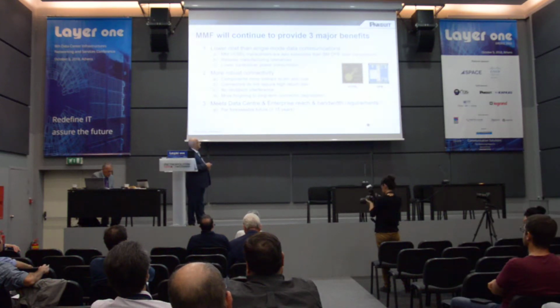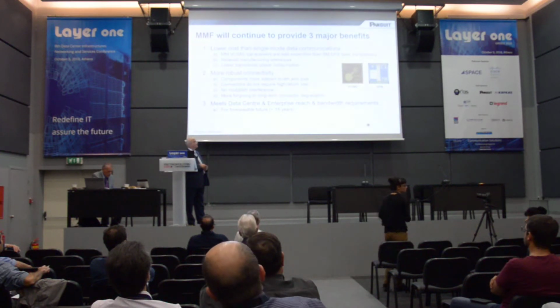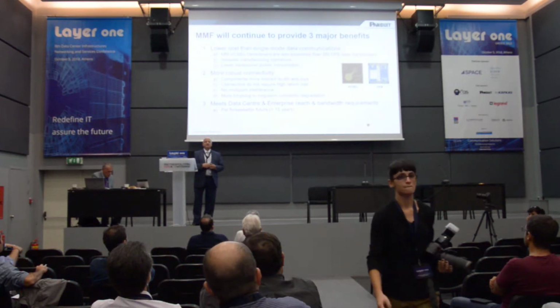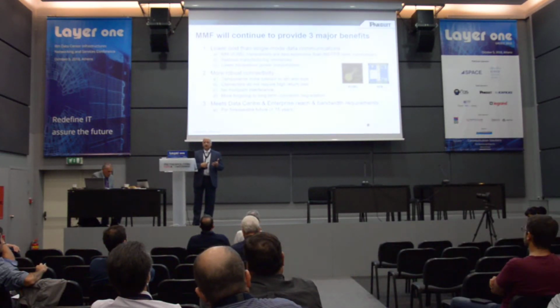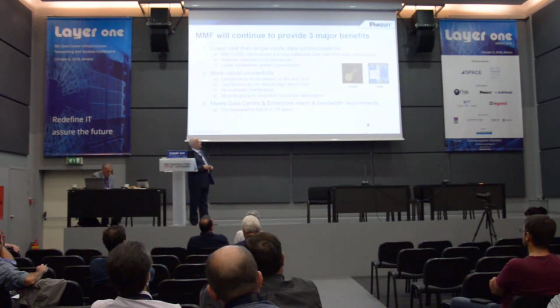I have an image here. This is a VCSEL. This is a distributed feedback single mode laser. The difference between single mode lasers and VCSELs is that DFB lasers are edge emitters. All single mode lasers are edge emitters, which means that the light actually comes out of the edge of the device, as opposed to coming out of the surface through this lens area here. Because it comes out from the edge, after you manufacture the laser, you have to then dice it and mount it onto a header, onto some material.